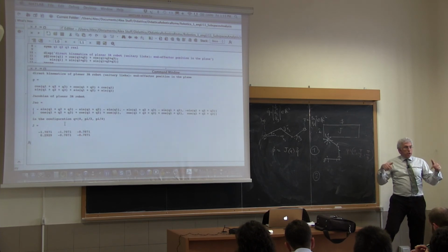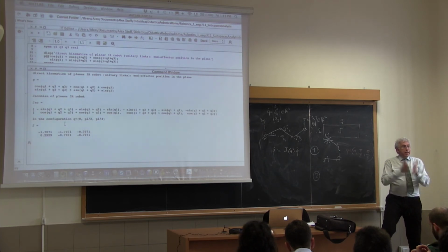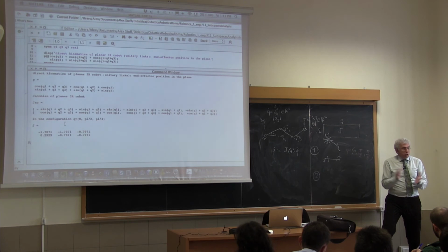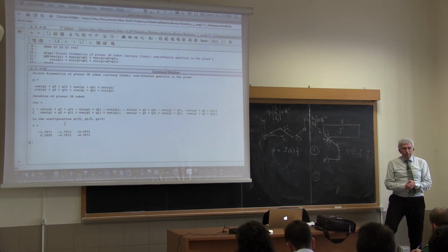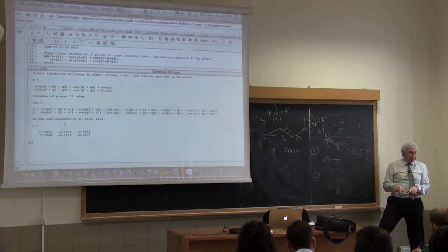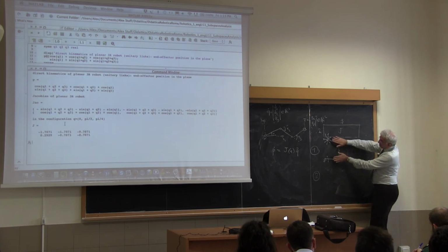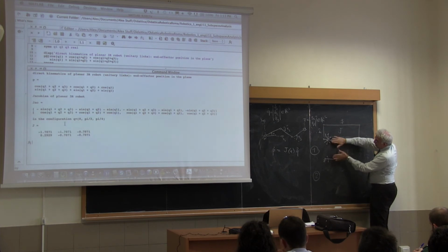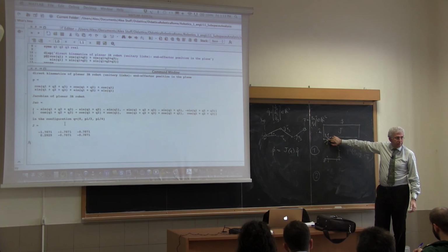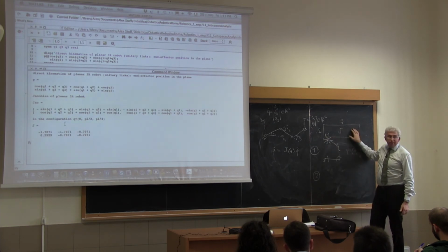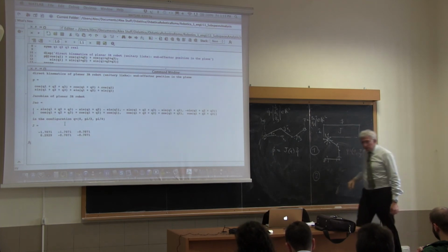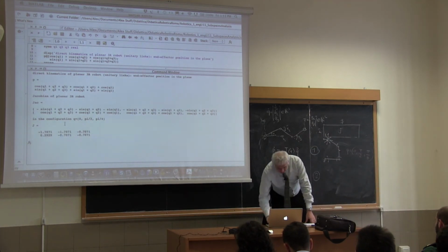Which means the null space of the Jacobian is different from just the 0 vector. And the answer is again yes. In fact, you can see it here. You can play around like a parallelogram and move this joint so that this end effector remains there. Okay? And this is because this is a 2×3 matrix.